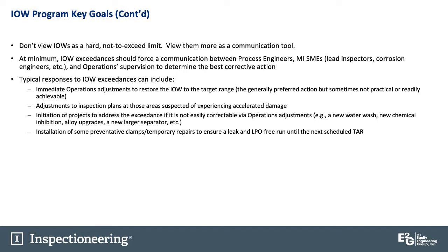It's always good to pre-plan those types of changes versus having a failure and then realizing you need to make those changes on an expedited basis. So by having IOWs in place, it gives us a much better opportunity to do pre-planning for those types of projects that will help manage our mechanical integrity over the long haul.